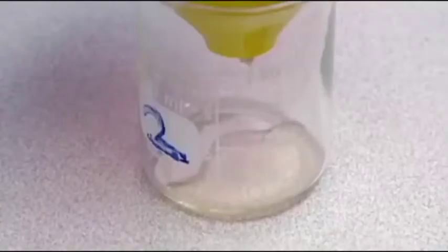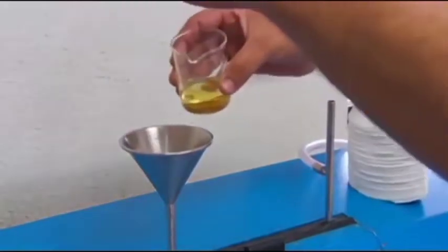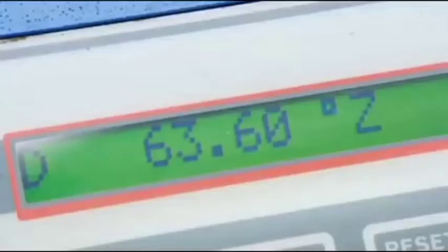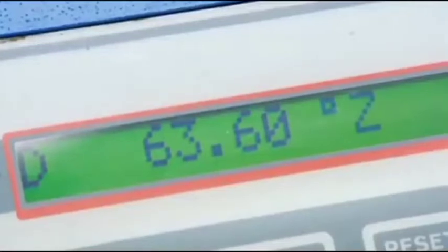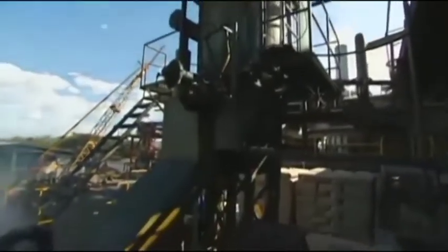2. The continuous pressure feeder. The continuous pressure feeder consists of a pair of feed rollers mounted in front of the milling opening. The input of bagasse is better or guaranteed, so that the milling capacity can be increased. The diameter of the rollers varies between 60 until 100% of the diameter of the mill rollers, generally around 80%.